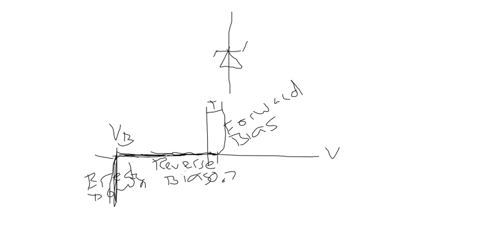And what that does is, once again, just like on the previous page where I used a stack of 3 rectifier diodes to lock in 2.1 volts to a load resistor, whatever voltage I want to choose, I have to buy a diode that has the voltage I want to use. I can't use one diode and get different voltages. But if I know what voltage I want, I can purchase a diode that has something very close to that voltage. So let's look at an example of how that would look in a circuit.